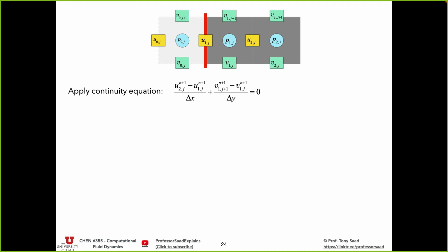So you take that continuity equation, and then you recognize that u^(n+1) for all j, u1, this u over here is 0 because it's a wall. It's an impermeable wall. There's no flow coming in, so it's always 0. Okay? So I can set this guy to 0 over here. This guy would disappear. So I'm doing the math for the continuity equation. So this would imply that, at least we got rid of this term here.